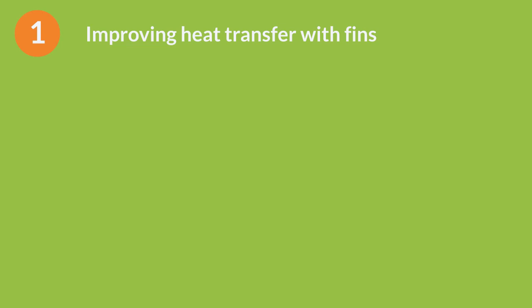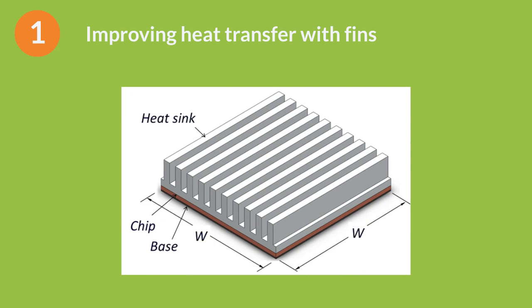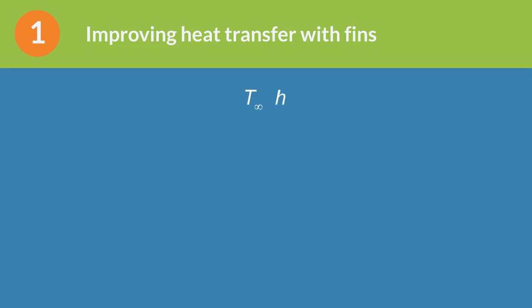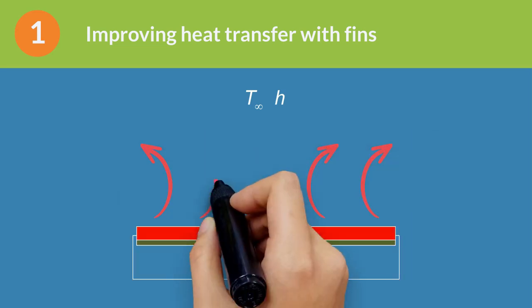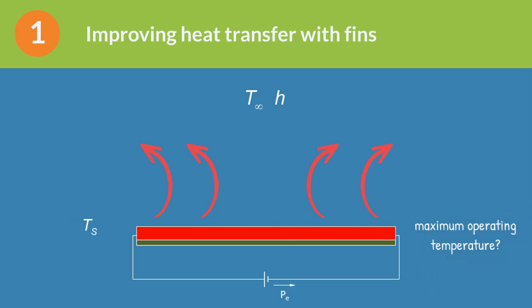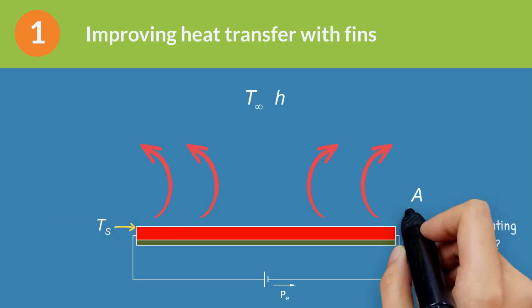Let us start thinking about why we need to put fins. Think about an electronic chip with a heatsink on top. This heatsink has several fins. Why? The electrical power consumed by the electronic chip is converted internally into heat. The higher the electrical power consumed, the higher the heat that must be dissipated to maintain the chip at an operative temperature. When the electronic chip increases its temperature due to the internal consumption of electricity, the first phenomenon that appears is free convection with the ambient air.